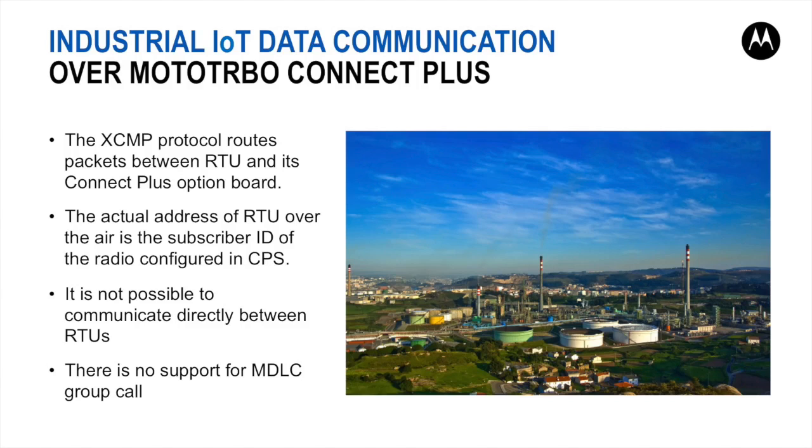There is about 2.5 seconds for the FEP from the LAN and 7.5 seconds per RTU from the radio delays. During this time, all communication via the physical connection is withheld. So the best practice would be to send to each RTU separately.